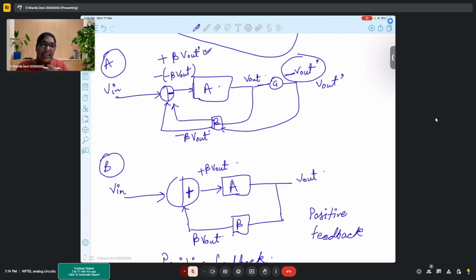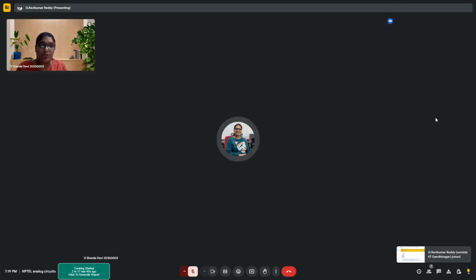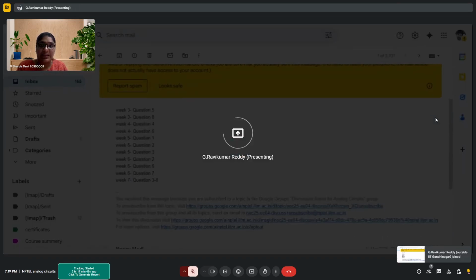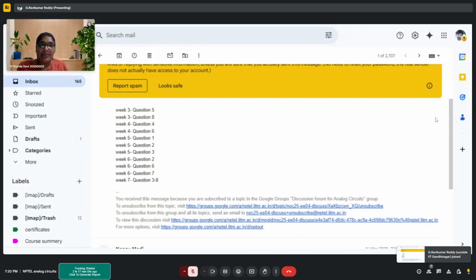Do you understand how the equivalent positive feedback behavior is coming, which is similar in both the cases? Yes, ma'am, that is okay. But how can we know whether it is in the feedback path or in the gain path? And is it a small signal model of a transistor, or which element? More or less, it should be a transistor because it's a two-port device. By seeing that minus sign, we cannot conclude.